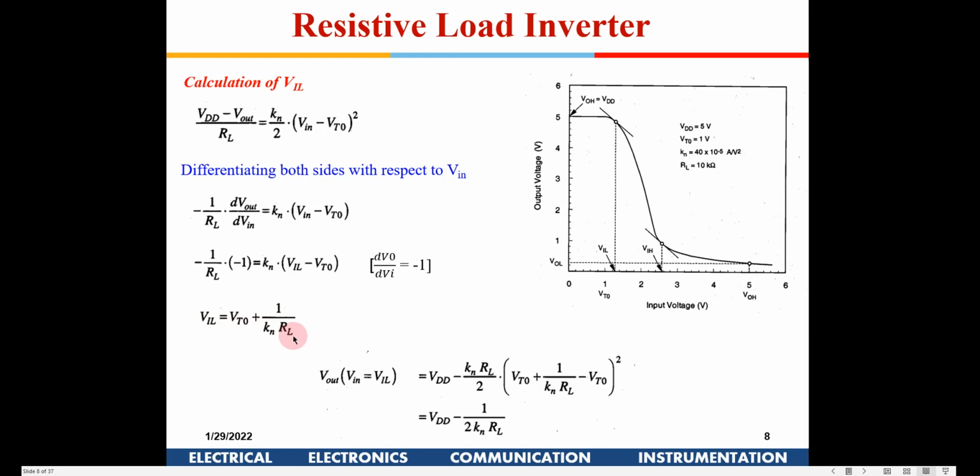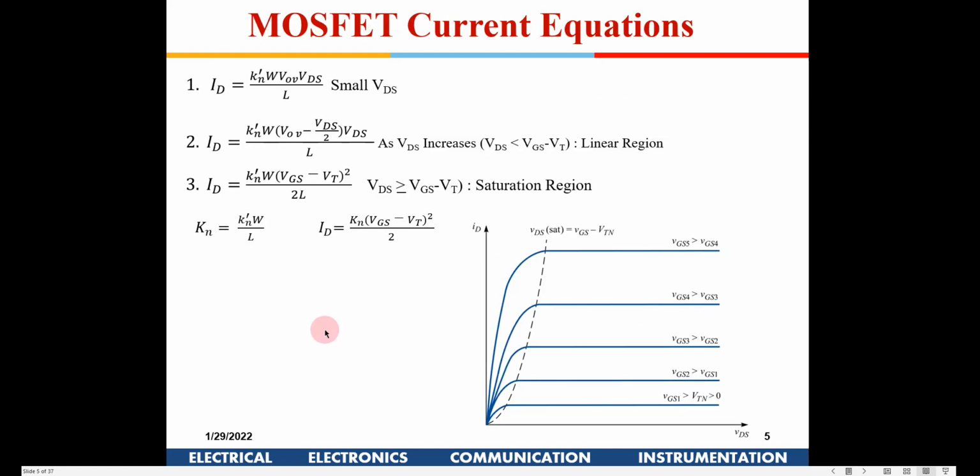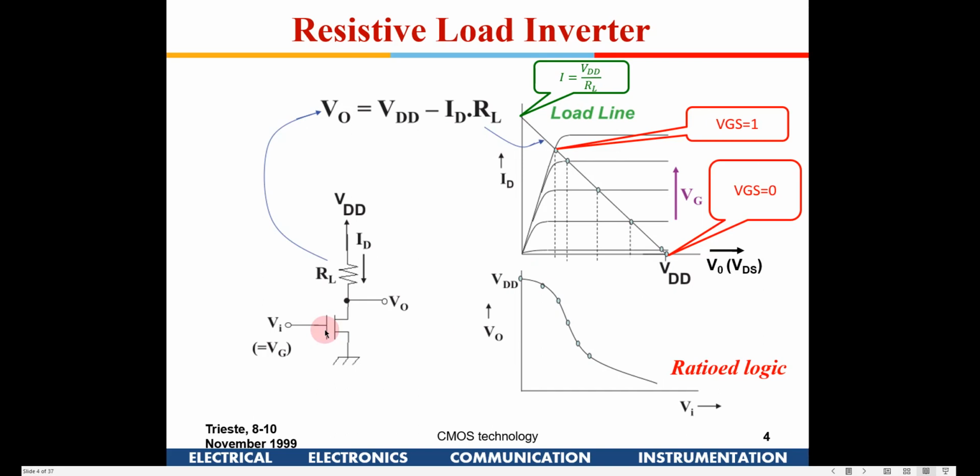Sir, one question. Yeah, tell me. For VOH, if you go with the resistive load, when the input is zero, the NMOS is basically cut off, right? Then V0 will be VDD minus ID RL, right? RL will be something because we are putting the resistive load over here. So VO will never be equal to VDD, right? If ID is 0, then...